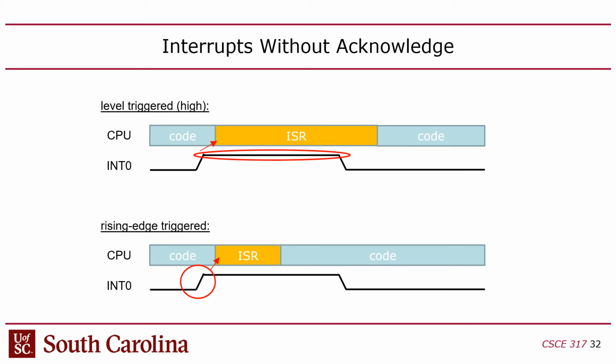Yes? Is the ISR just like a cycle of checking interrupts? No, it's more than that. Depending on which peripheral it is, the ISR usually is a sequence of programmed I/O operations that service it. So the interrupt goes high, and the first thing the CPU does once it gets into the ISR is pull a status register from the peripheral and say, what's going on, man? Why'd you interrupt me? And then through that status register, it'll know